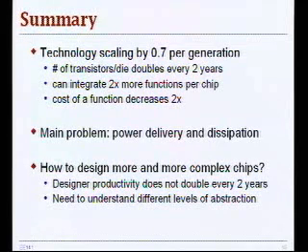And the answer for that, as we saw last time, is that you need to understand different levels of abstraction and simplify the problem, treat your design components as black boxes and have some macro models that you can propagate across multiple layers of design abstraction. And this also led to the development of automated tools that aid in design of complicated chips.